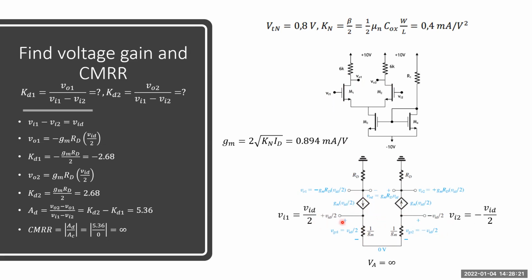It comes from the polarity of VGS actually, because current value is basically equal to gm VGS for the MOSFET. For the M2 transistor, we defined a negative VGS here, which is VID over 2. That's why the current direction for M2 is toward the upper side. Actually, it's flowing into the drain, looks like, okay?